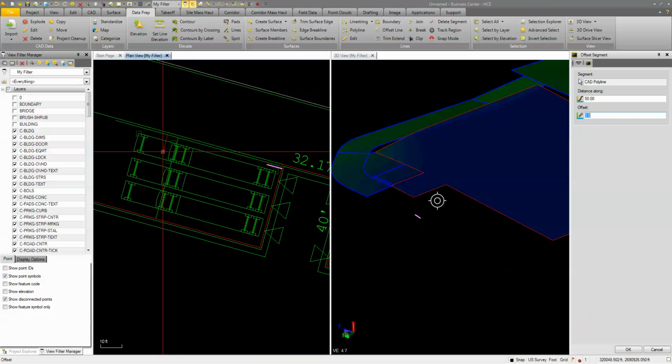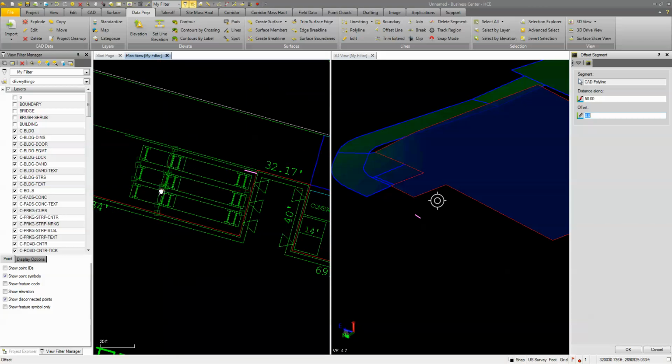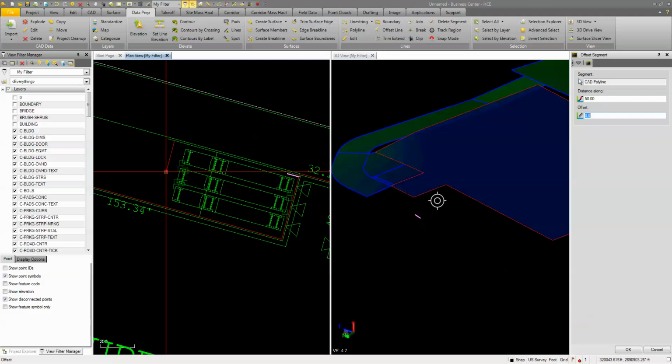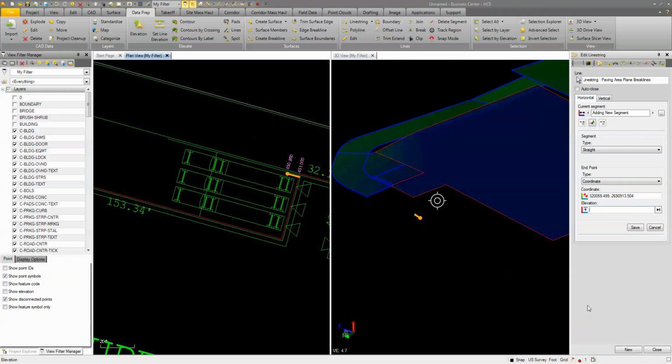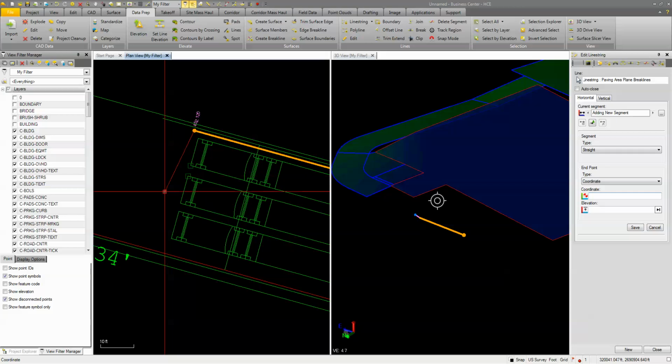So that's not where we want the ramp to break. We want the ramp to go out about 70 feet. So if we put in 70 for the ramp, and the offset again is going to be -1 foot, we'll click OK to that, and then the slope is going to be a +2%, and you can see now it comes up to the front of the ramp.